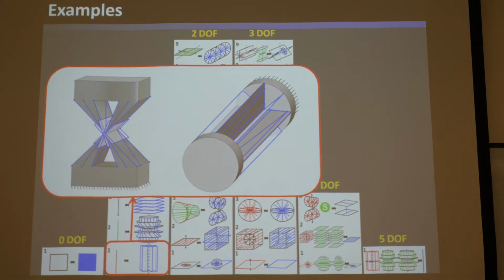Okay, so here's two examples of other flexible elements, parallel flexible elements that achieved a single rotation. Okay, remember we showed you the living hinge, but this is a slightly different one. This is two triangles cut out of two opposing kind of triangles. Here they all lie. The rigid body's on top and this rigid body's on the bottom, and sure enough, this satisfies the conditions.